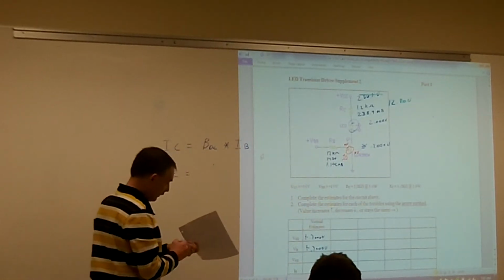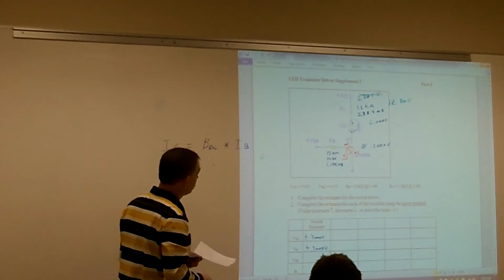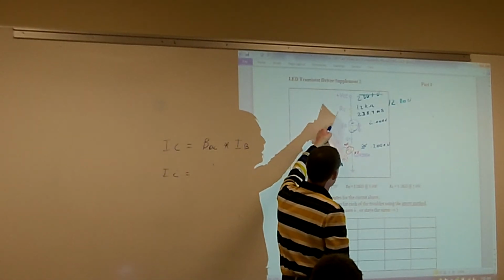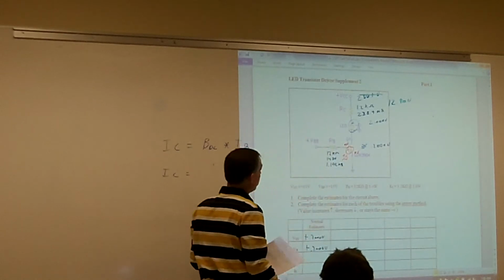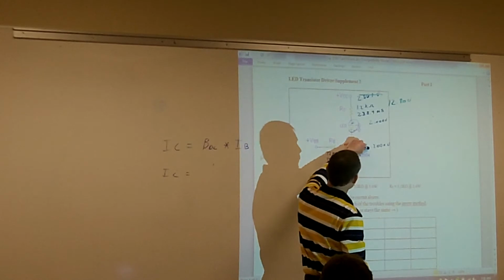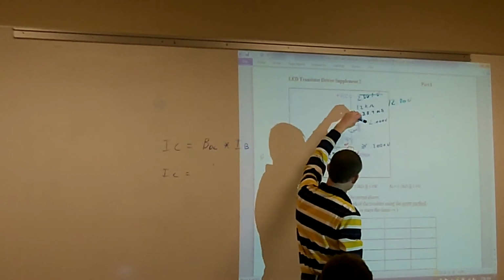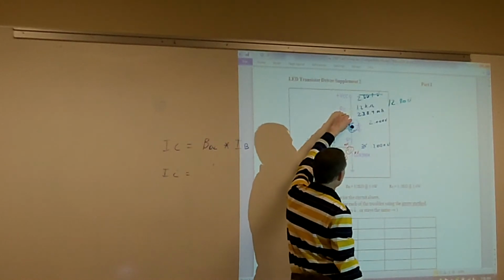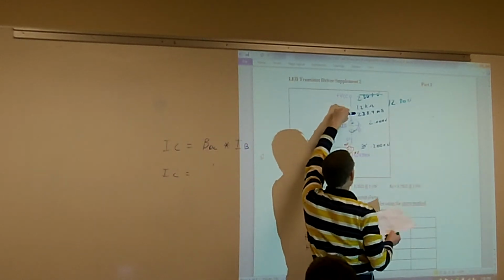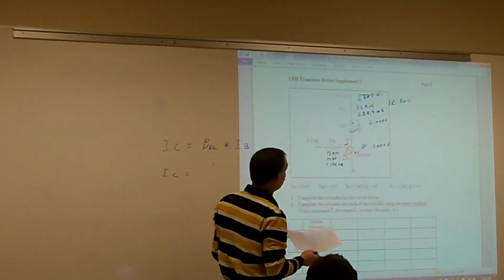Okay? Because we really want to treat these transistors as switches, so we really want to either fully turn that transistor on or fully turn it off. So we're fully turning that transistor on. The collector to the emitter voltage is dropping down to 0.2 volts. It's going to take its voltage first. The diode is also going to take its voltage, and then the remainder is going to be dropping across RC. And then that gives us 12.8 volts.